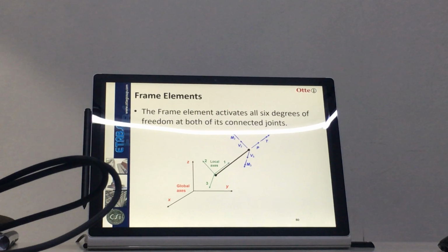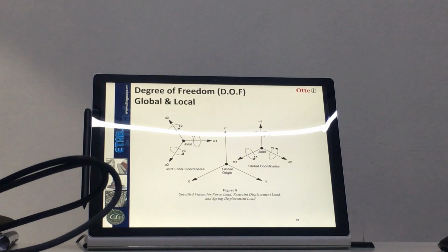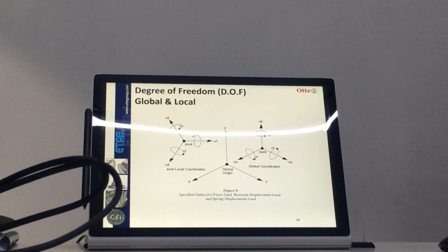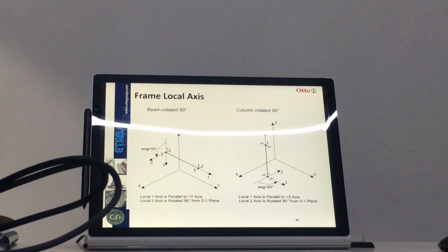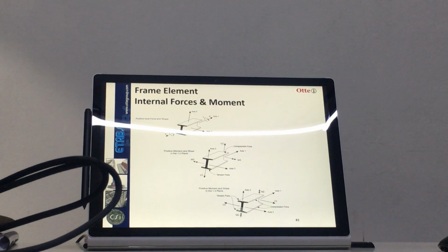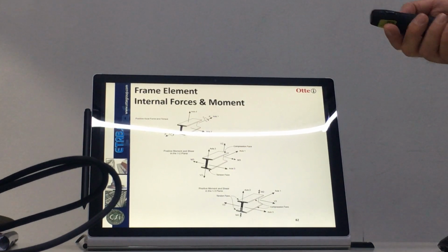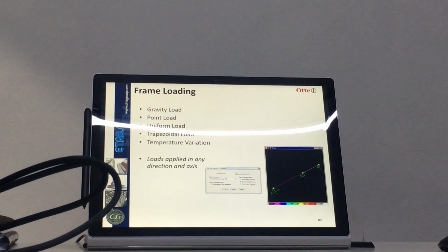We talk about the degree of freedom. Basically, in a full finite element analysis, each node has 6 degrees of freedom. 3 translation, x, y, z, and 3 rotation about x, y and z axis. Right? So that is how it shows you the M2, M3, and then strong axis bending, everybody knows, right? I don't think anybody has to explain.